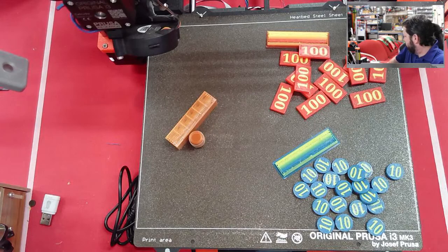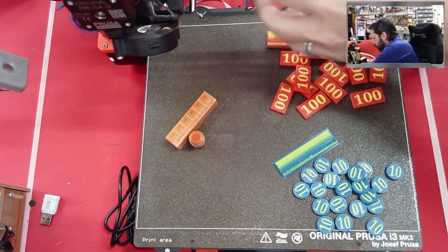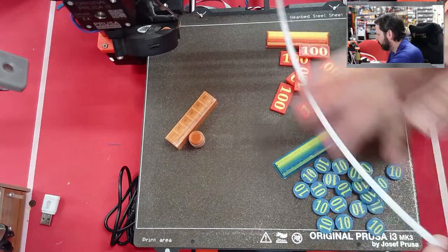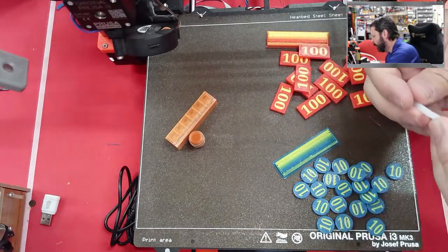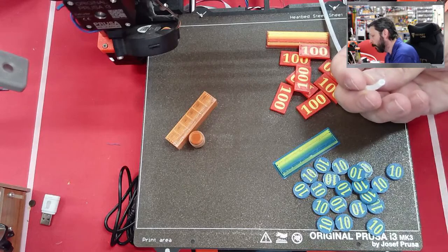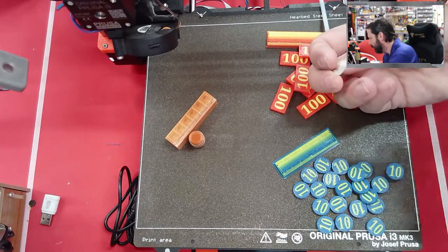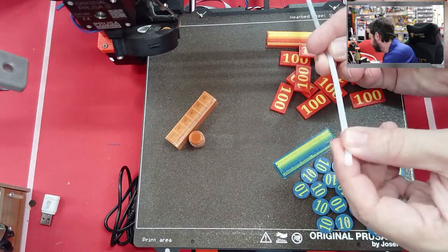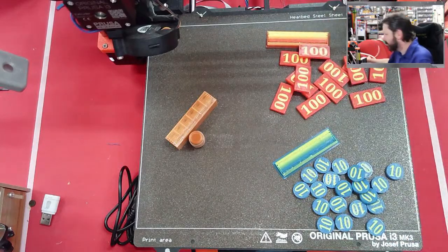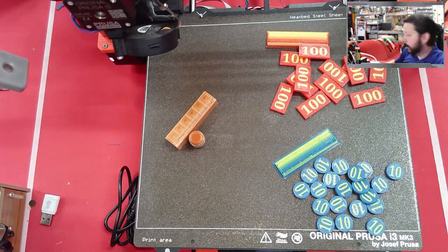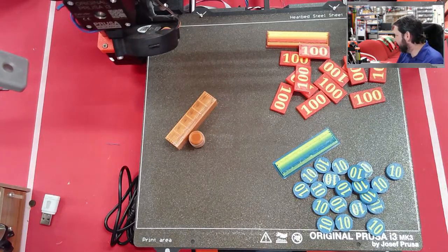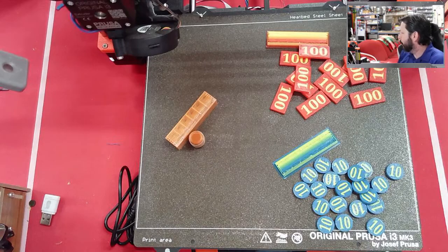This machine uses its own Bowden tubes. There are 5 of these tubes that lead into the machine. The filament I was using for one color that I kept printing with was just a little too tight, and there was too much friction in this line. I fixed that by not using that filament. I switched it out for another one. I will more permanently fix it by changing out these tubes for a slightly larger diameter tubing that I ordered. That should fix that problem. There was too much friction in the tubes and it just wouldn't pull the filament through.